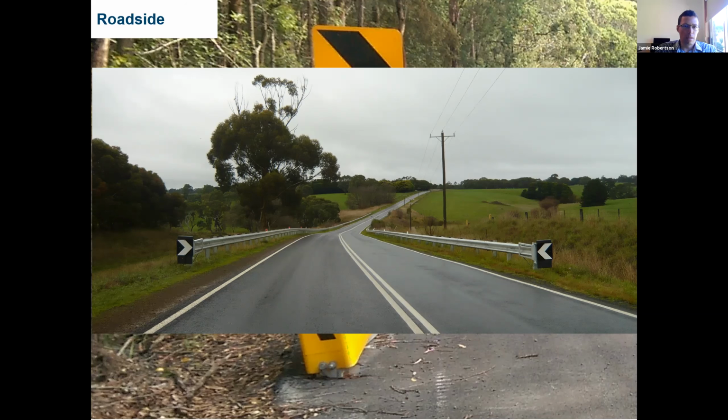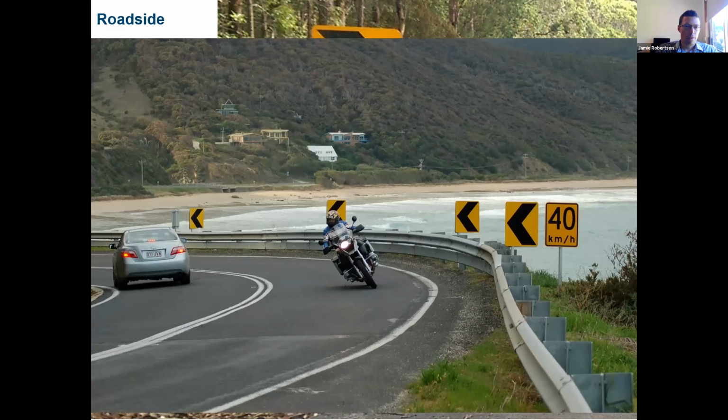Roadside barriers are typically flexible. We choose as flexible a system as we can provide subject to the site constraints, as opposed to bridge barriers, for instance, where we really beef up the containment level and generally prefer a concrete barrier. Here we have a windy road, popular with motorcycles, and you can see a motorcycle rub rail at the base, and Ken will talk more about these sorts of treatments shortly.